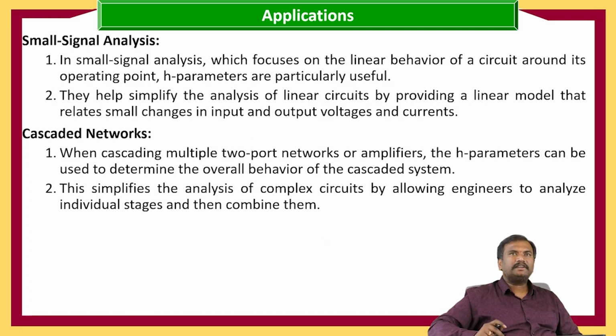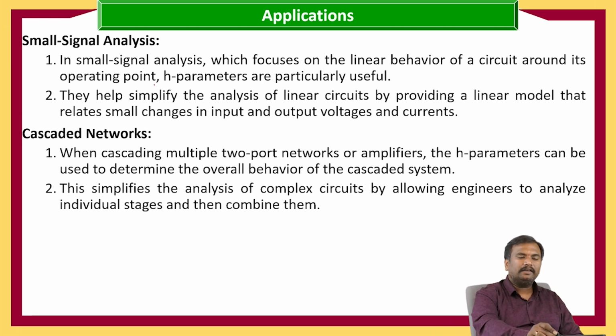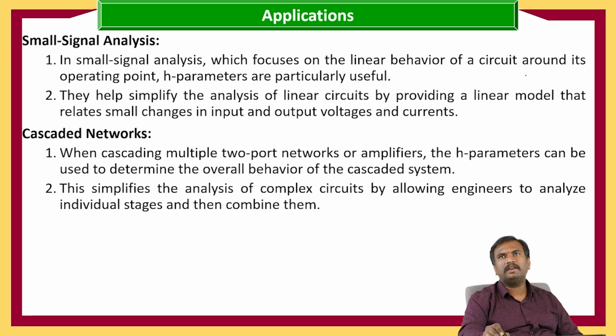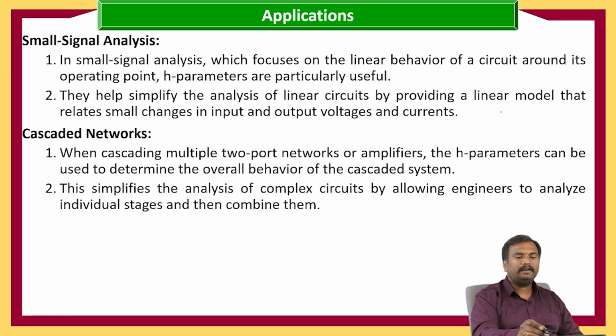The next one is small signal analysis. In small signal analysis, which focuses on the linear behavior of the circuit around its operating point, H parameters are particularly useful and they help simplify the analysis of linear circuits by providing a linear model that relates small changes in input and output voltages and currents.